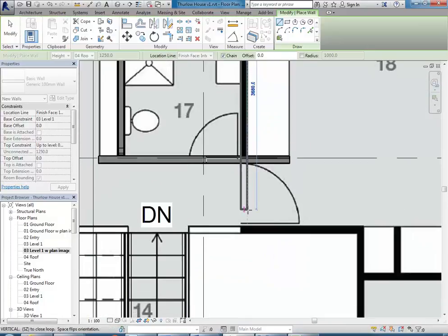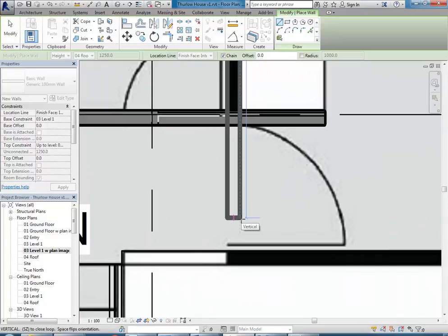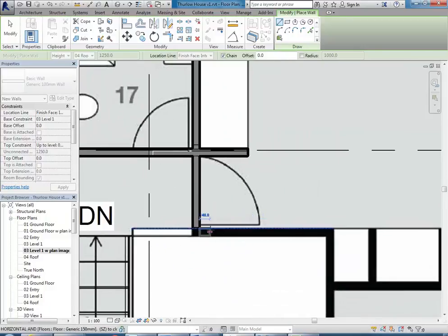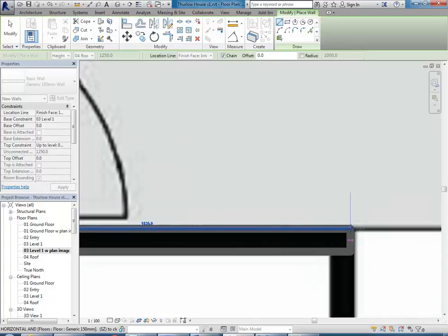And so the most important thing here, see there's a door there, so it's really important that you don't stop the wall here. Even though you can't see a door, you need to take the wall down so that you've got something to place the door into. And also remember here, the wall there goes over the floor, so the wall there should go below your floor.